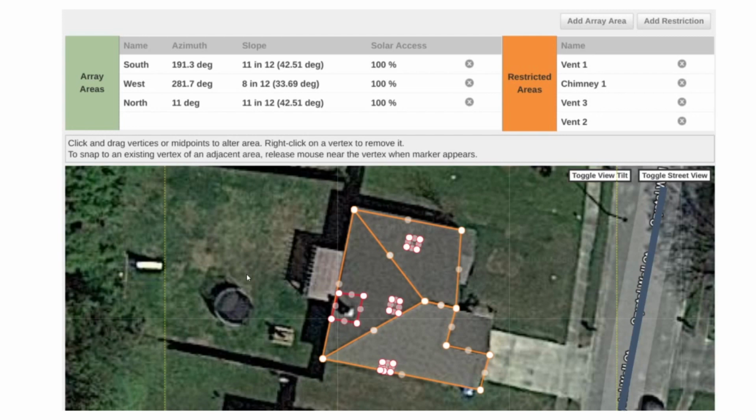So here we've mapped out different obstructions on the rooftop. These pre-existing holes in the roof, chimneys, plumbing vents, valleys that are shingled over or flashed together. These pre-existing holes become common leak hazards after the solar array is complete. This is because most workers on the roof are stepping on these locations. A risk that is increased, particularly with a compact array design.